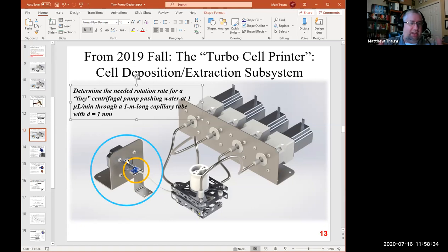And my main research area is actually Tesla turbines. Tesla turbines are pretty much the fastest rotational prime movers that exist before ball bearings and things start breaking down. For a while they had imagined, this would have been super cool if it had worked out this way, using a Tesla turbine here instead of a DC motor to turn this pump, because they had originally anticipated something like 100,000 or 120,000 RPMs, which is way faster than a typical DC motor can turn.